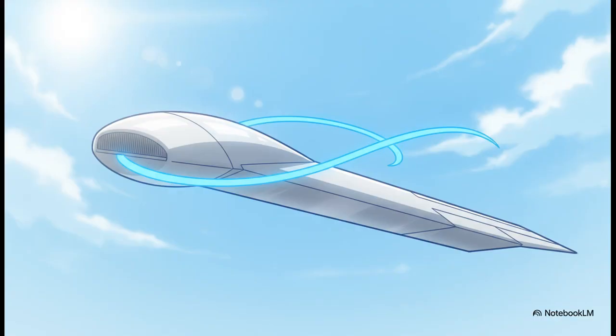And this brilliantly illustrates that difference in camber. You'll notice the upper camber has a much more pronounced, sort of scooped curvature to it, while the lower camber is usually a somewhat flat surface. This specific difference in curvature between the top and the bottom isn't just for looks. It is the fundamental design element that ultimately determines the wing's overall aerodynamic efficiency.